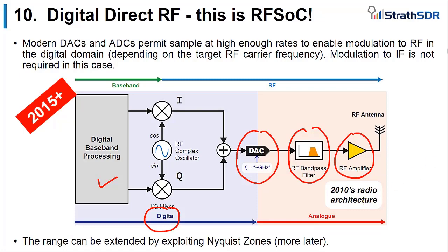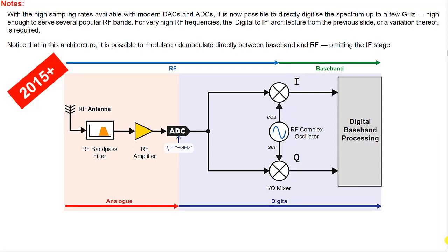And at the receive side, well, we also are using RF ADCs. So we are sampling at gigahertz, and my oscillators and so on, well, they're running at gigahertz, and these are all software-defined radio, right up at the QAM physical layer stage. And then the rest of the digital baseband processing, my 2G, 3G, 4G, 5G, whatever it might be, of course, will be done on the RFSoC FPGA.